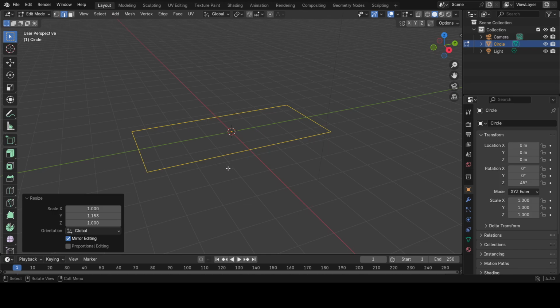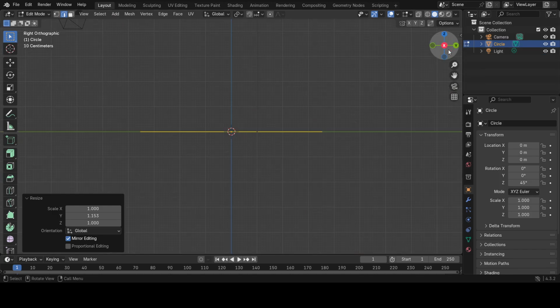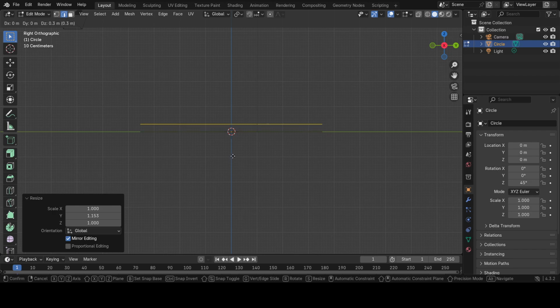And there's a couple things that we want to look at while we're doing that. So the first thing, which I thought was very interesting, is if we were to copy this while in the edit mode. Let's go ahead and do that now. I'm going to do it from the X or right view and Shift D and hold down Control.